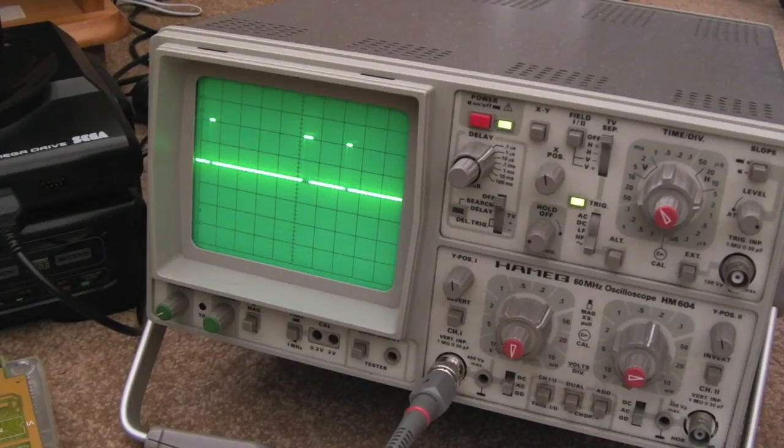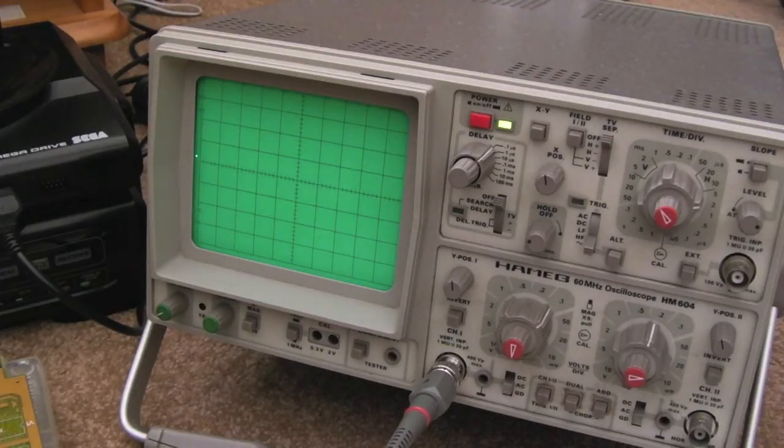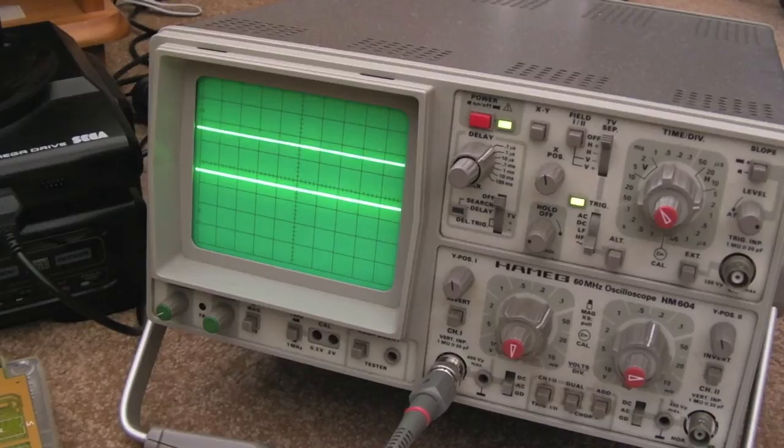Right, that's YM music for the chip, so it's not PCM. There you go. As PCM kicks in, see the high level is back again, so you've got a good transition there between logic high and logic low, which is what we'd expect, and that's like the 4th or 5th pin along. This is the next pin. Look, that's not correct. So we've got yet another data pin that has got a failed pull-up.